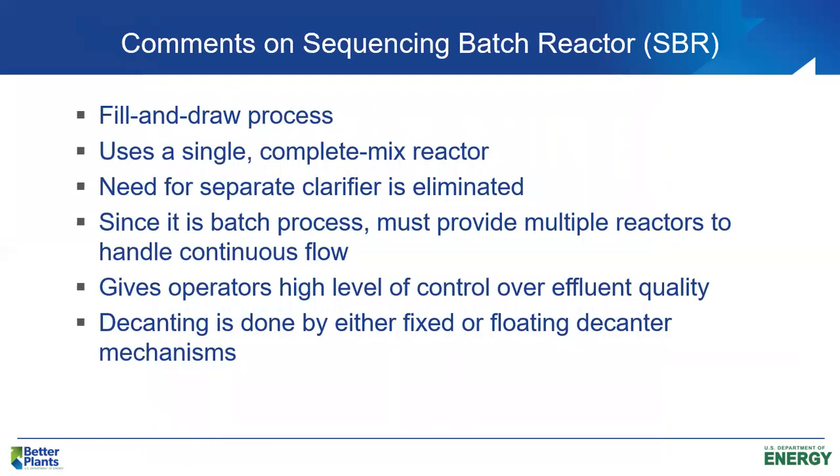So, comments about the SBR process. Again, it's a fill and draw process. The reactor is basically completely mixed, because when we turn on the air during the react period, there's good mixing in the reactor. Sometimes it's supplemented by mixers.